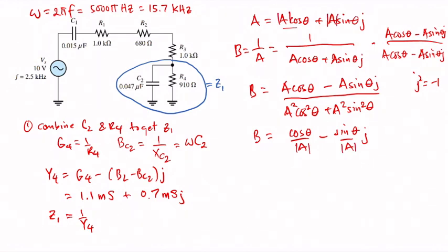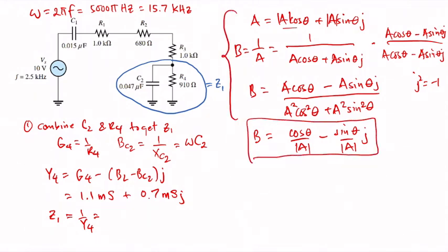Now remember that a here is the amplitude, just to be clear that that's the amplitude and not the phasor component. You can compute manually using this equation or this technique, or you can simply use MATLAB. So in MATLAB, Z1 will give us 627 ohms minus 421 ohms j hat. Now that we've solved for Z1, this is the equivalent circuit there.